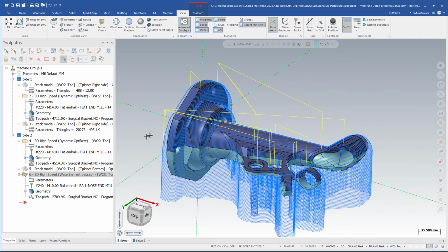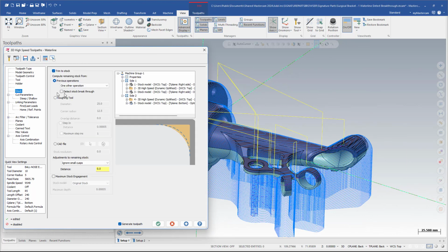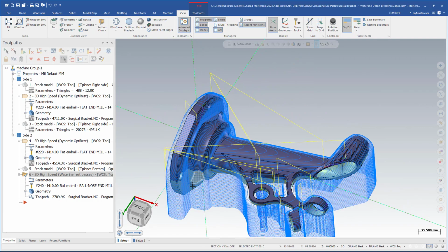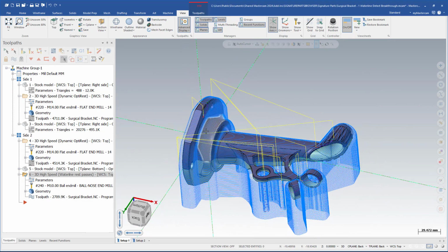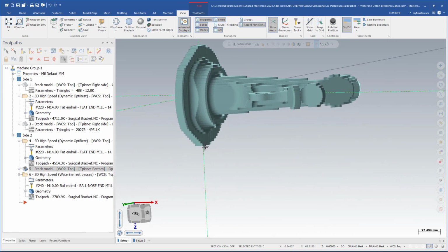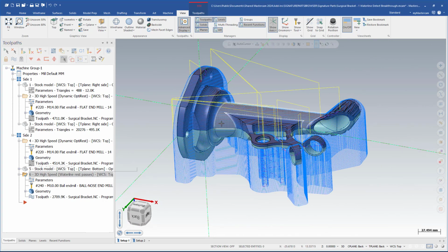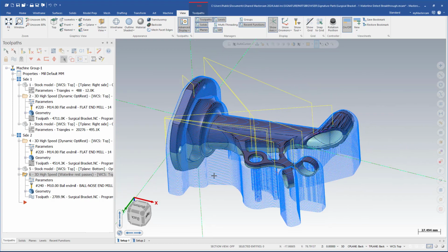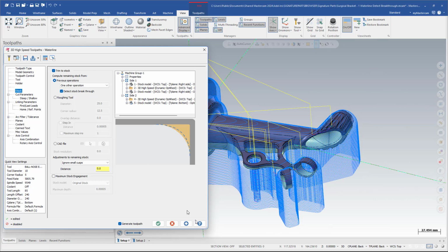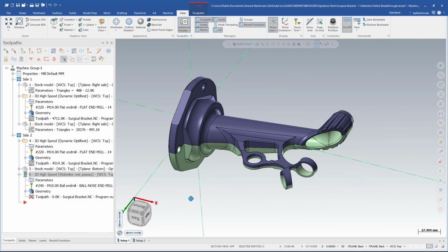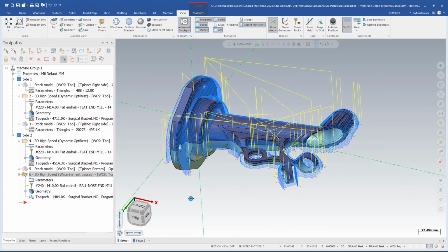Because the Waterline toolpath, even though it has the stock turned on and it's looking at that particular stock model, what it's basically seeing is the silhouette as the maximum size to cut, and then it sees that there is still stock all the way down here, so it's just running the entire toolpath to that depth. So what we need to do is turn on the option for detect stock breakthrough. And when we do that, this is going to shorten the toolpath to where it only will cut where it sees that it can actually hit material based on that breakthrough.